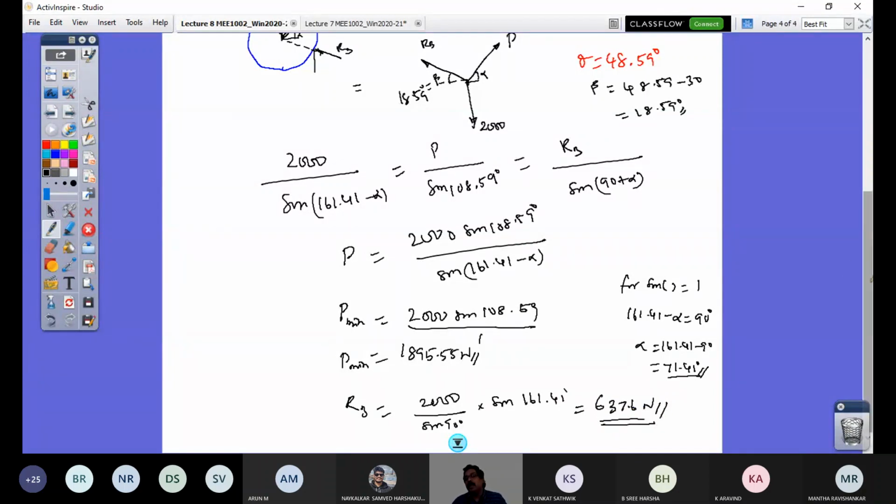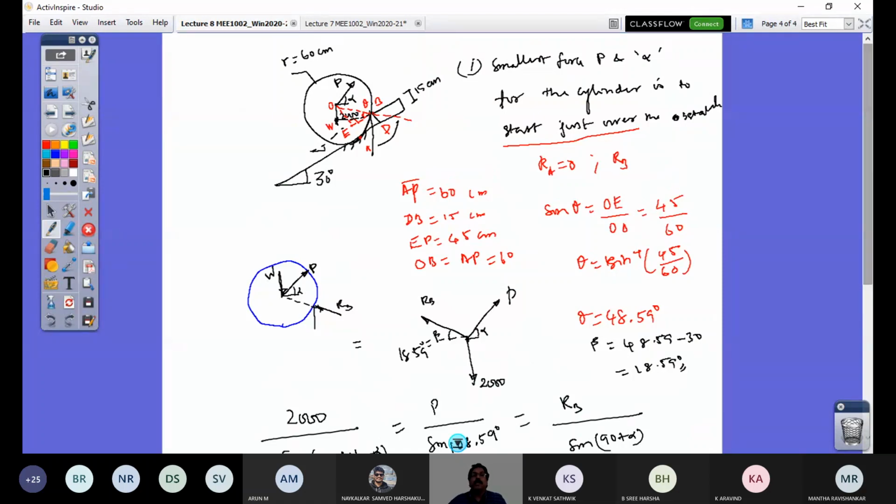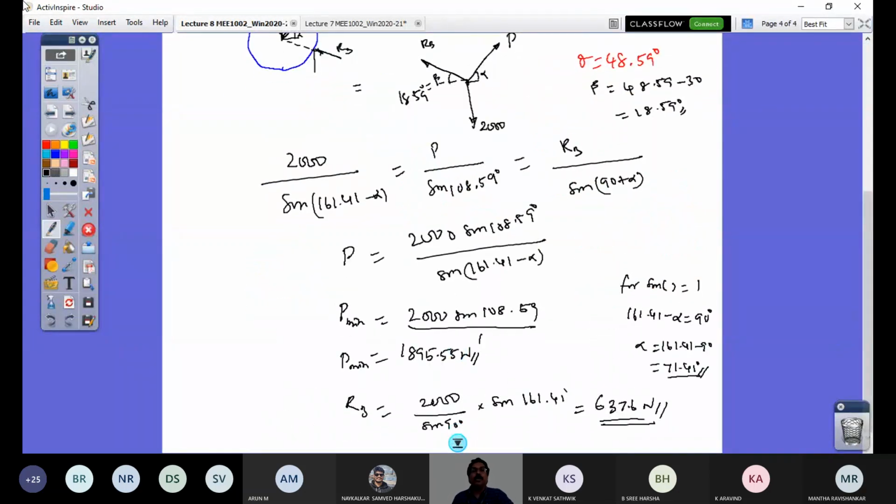So here the understanding is of three-force equilibrium. When I have P and weight concurrent here, the reaction should go through that point. That's the idea, and that leads you to find its direction through this triangle geometry and so on, and you are able to finish the problem. So I hope you have understood today's concepts of static equilibrium. I would be happy if you never make a mistake and fumble to understand the configuration diagram and FBD in the forthcoming classes. If you are good at it, mechanics is very simple, right?